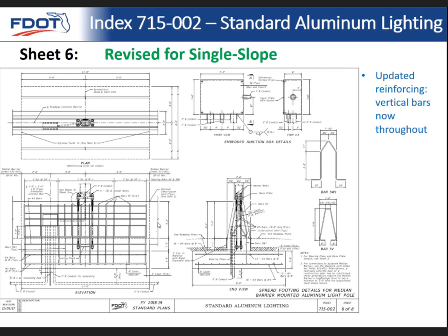Now, because for median barriers, we have continuous reinforcing, we've also had to change this segment that supports the lighting foundation to also have continuous steel so that it corresponds to the median barrier, which also has continuous steel.